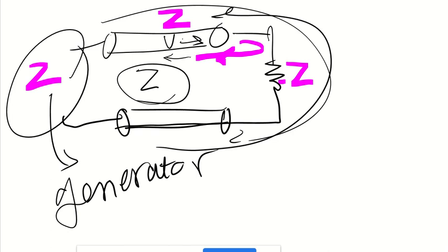That reflected part will come to life when there is an impedance mismatch between components. So, for example, if this is Z prime and this is Z, you have reflection of your signal. Your signal will reflect back. That's called impedance mismatch.